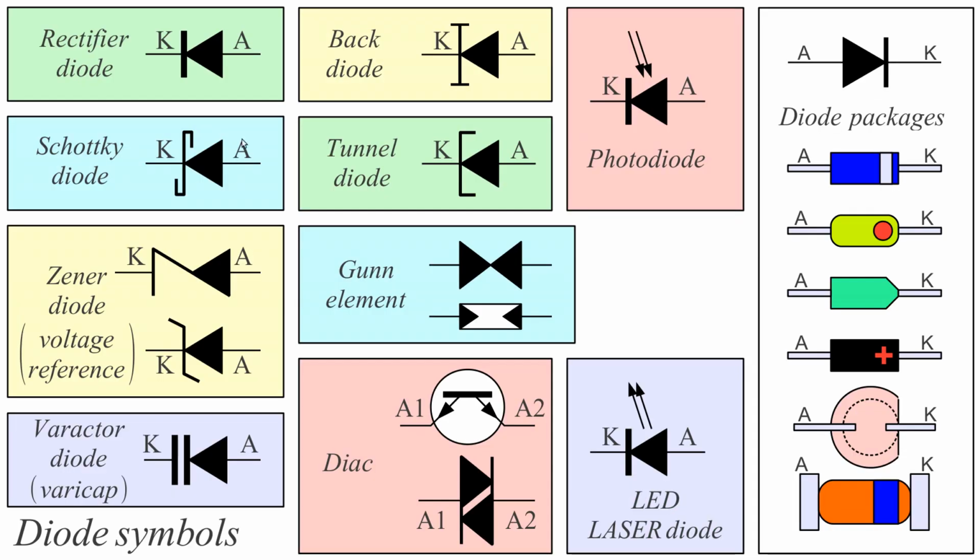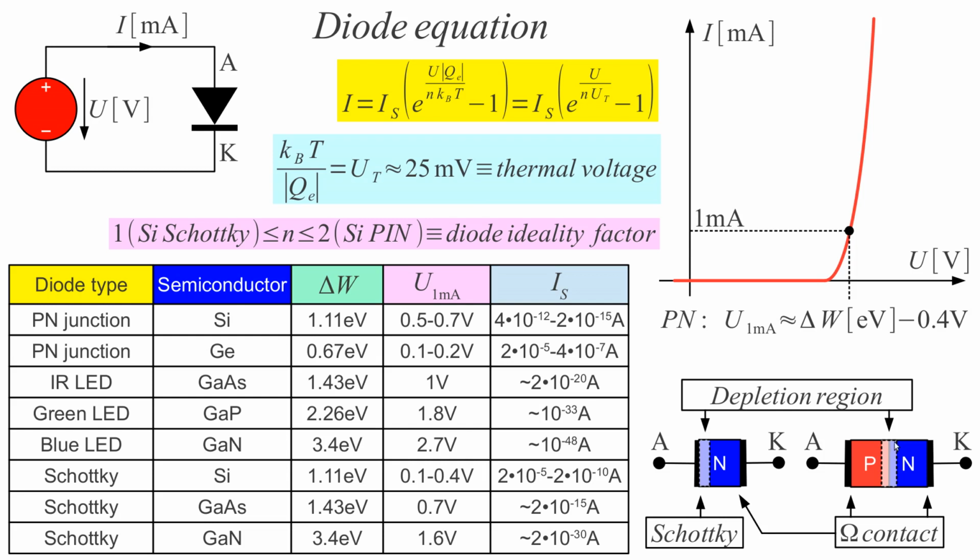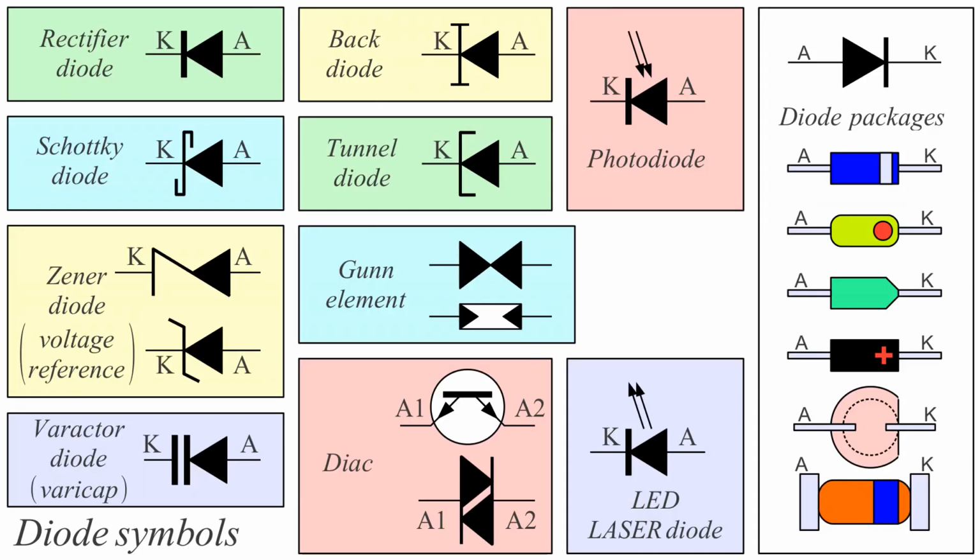So now the idea is to use this depletion region here. This depletion region without bias is not conductive. In this p-n junction, both p and n are rather lightly doped. If they were strongly doped, we would get a tunnel diode. And this actually makes a capacitor. If we apply a reverse bias on this diode, we can make this depleted region larger, and thus with the same area we have a larger spacing between the electrodes of this capacitor. We reduce the capacitance, so we can make tuning diodes. That's usually called a varactor.